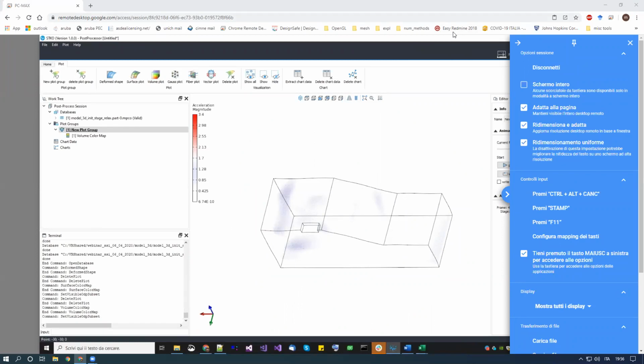Just a question. I have a question here. You said those are zero length elements defined between nodes of soil elements, but they're finite length, don't they? Are they actually two node link elements? No, they are not two node link elements. They are zero length elements. And in fact, when you run the analysis, you will see that they give a warning.